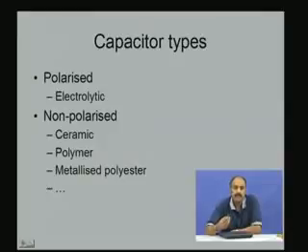It can vary from -40% to +100% of the value of the capacitor that is written on the nameplate of the capacitor. In the case of the non-polarized, you have the capacitors named based on the material of the dielectric that goes into it, the ceramic dielectric type or the polymer based, you have the metallized polyester. Metallized polyester has very low tolerances to changes in the environment, and therefore, they are used for frequency tuning applications, things like that.